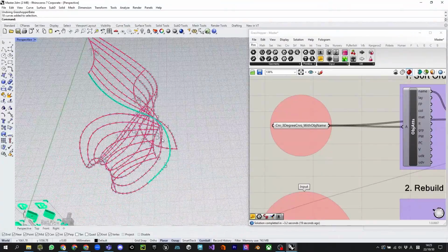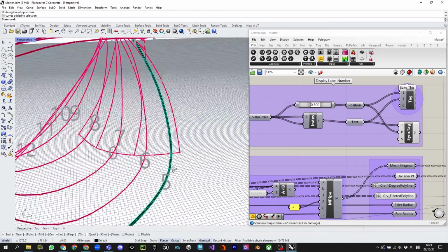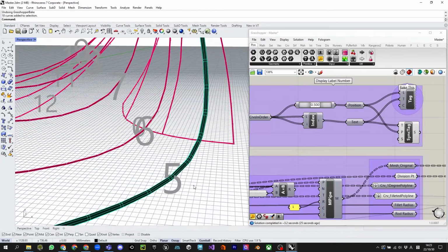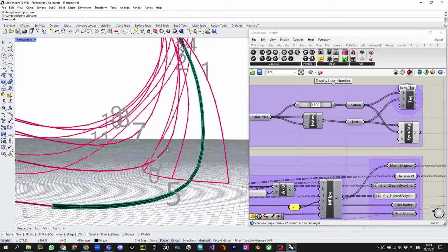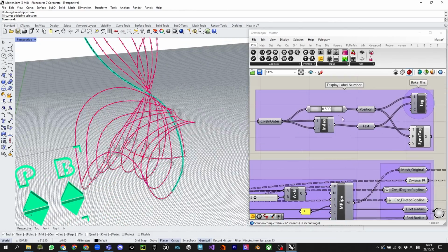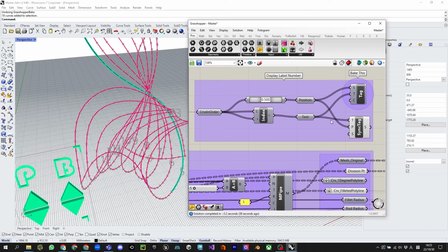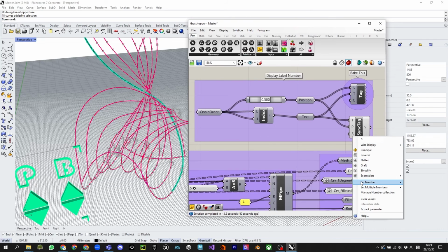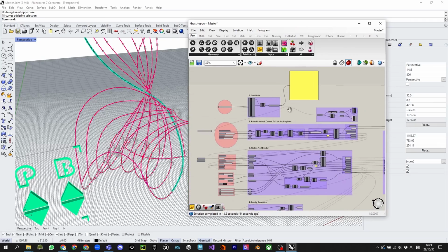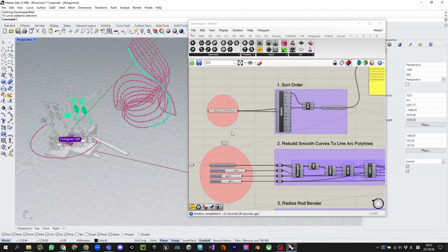So the Fologram text tag is set in millimeters, so you will see this exactly at this scale. That's really good. So you can adjust the text size if you want. You can right click, set a number here, and then change this number to change the font size. So that's the first thing. So you want to set up the order.